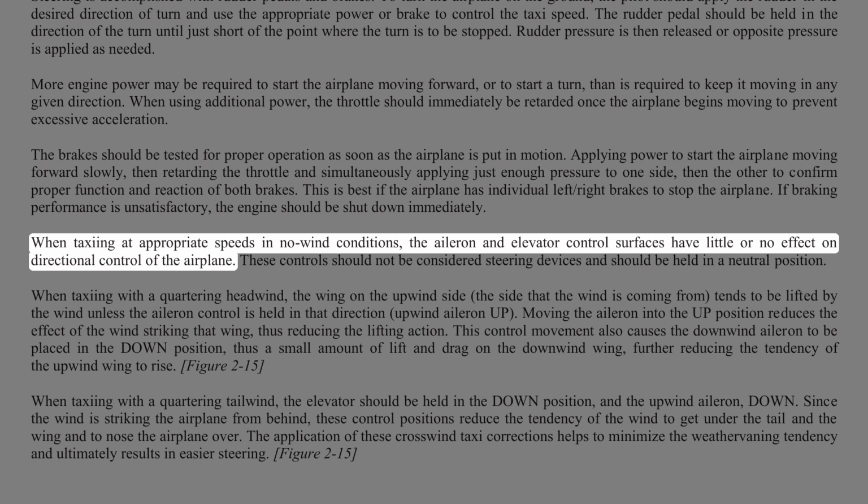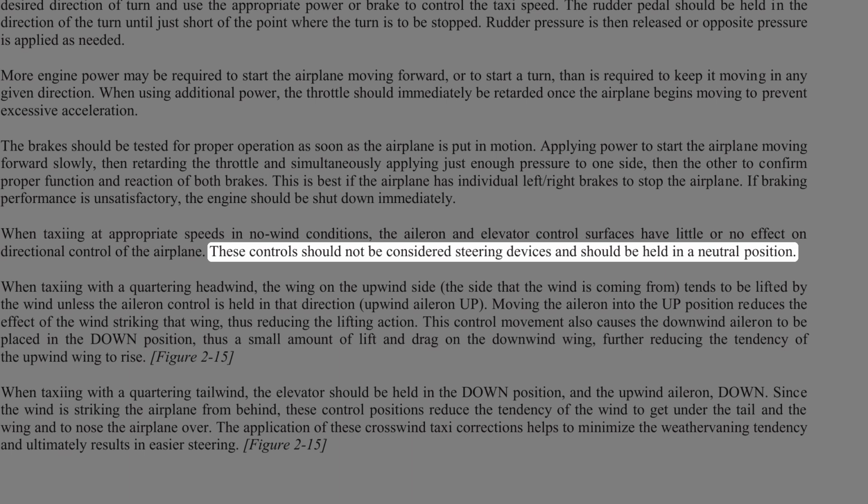When taxiing at appropriate speeds in no wind conditions, the aileron and elevator control surfaces have little or no effect on directional control of the airplane. These controls should not be considered steering devices and should be held in a neutral position.